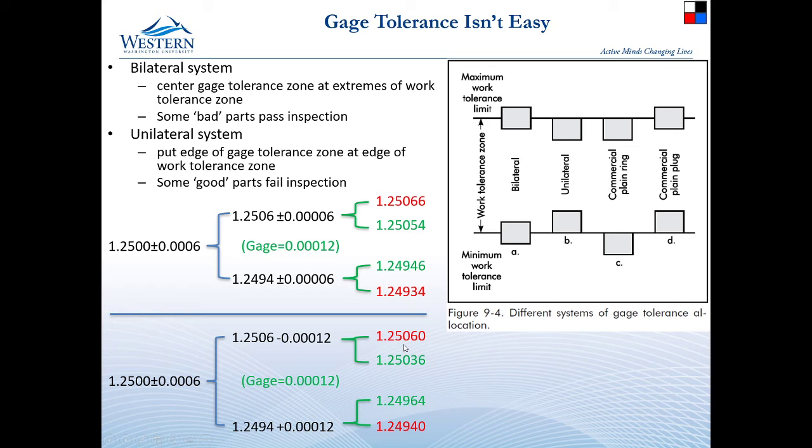If it's something that's not really critical, then maybe you would allow it to go. But one of the challenges with that is if you make something that is out of tolerance and you allow it to go down the line because you say it's not really that critical, then the question is, why is your tolerance band that small?